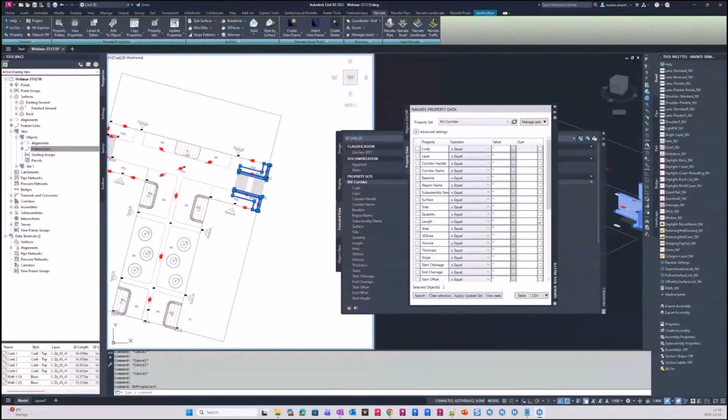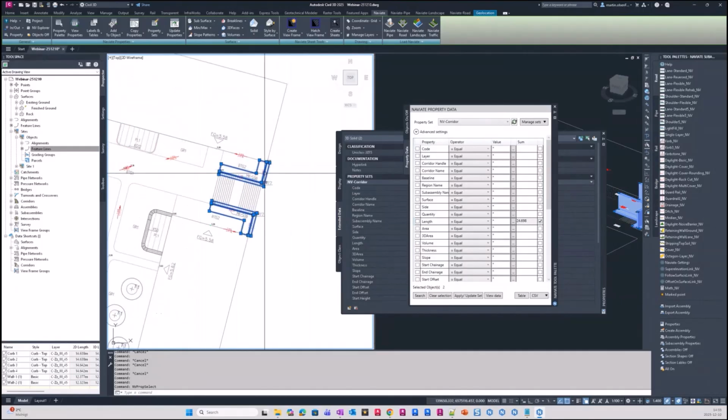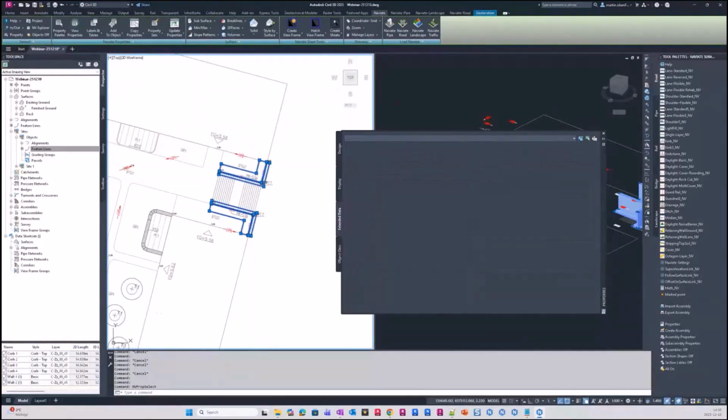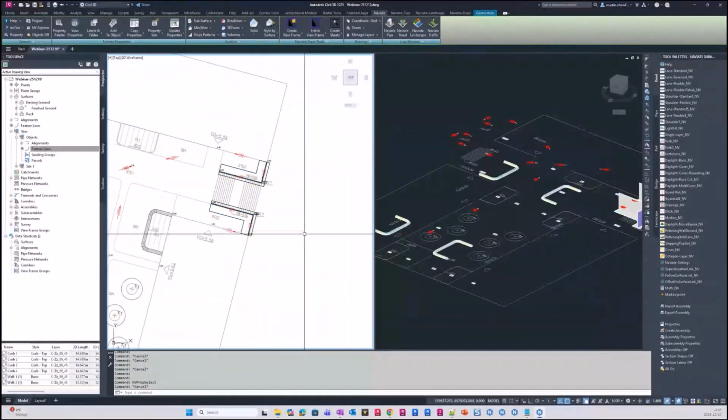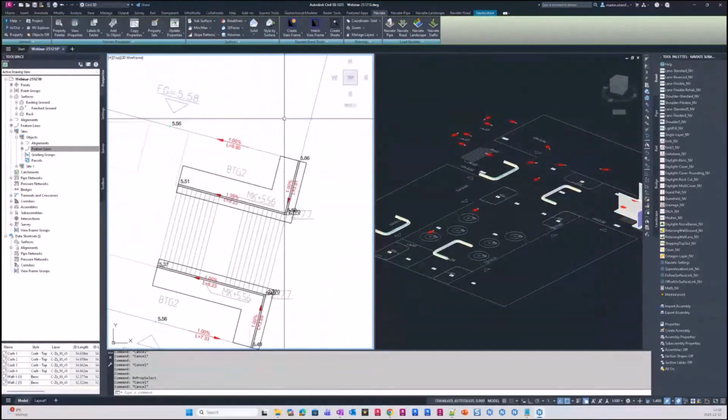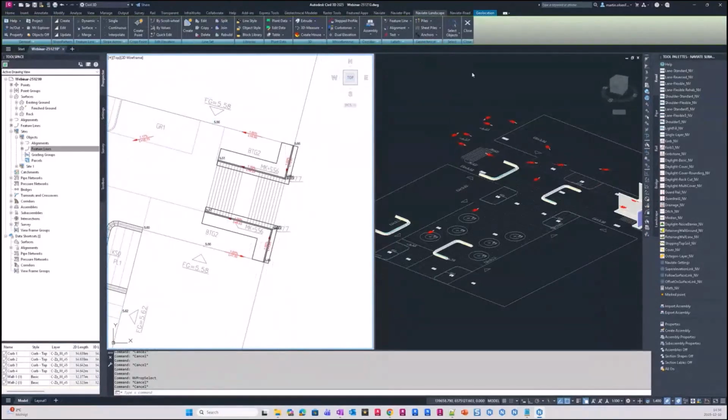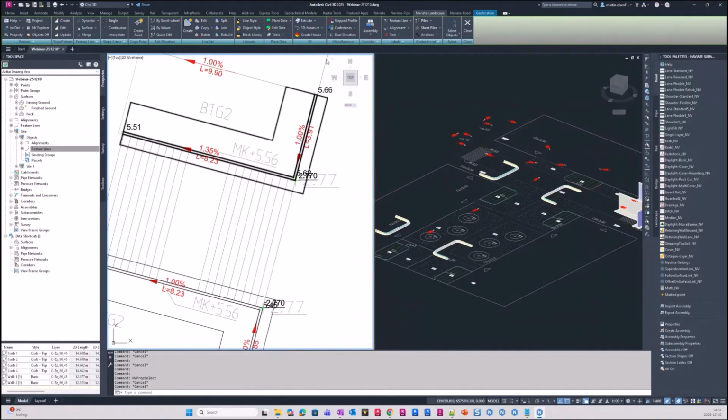And also do a sum on the length. So now I know that I got 24.7 meter of retaining wall, for example. So, and we can also use this function, 3D measure or extrude objects along line. Use the same line. So now I will create a fence with this line.